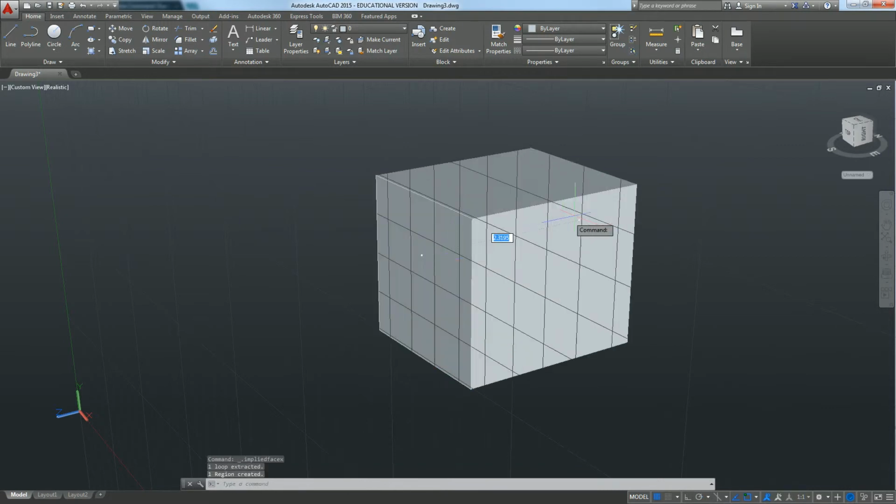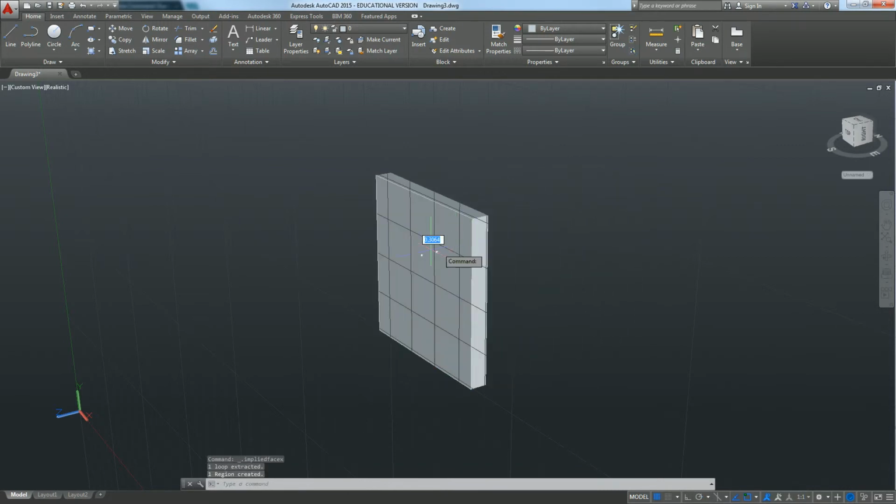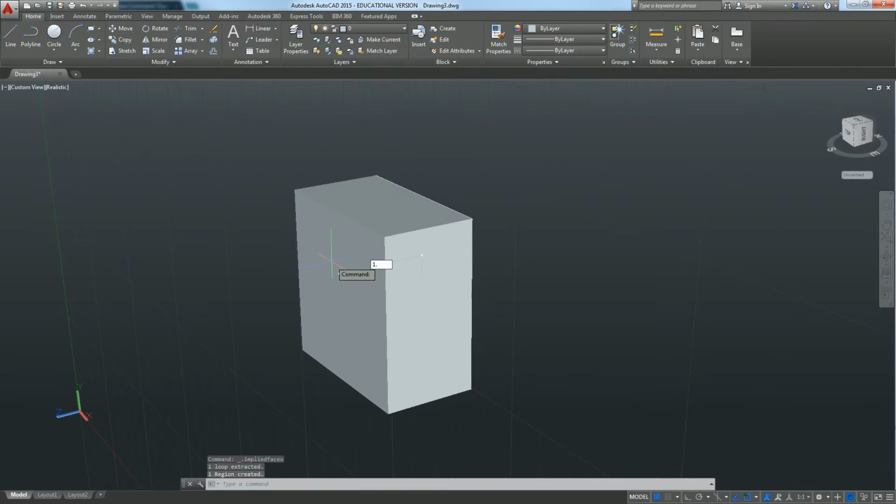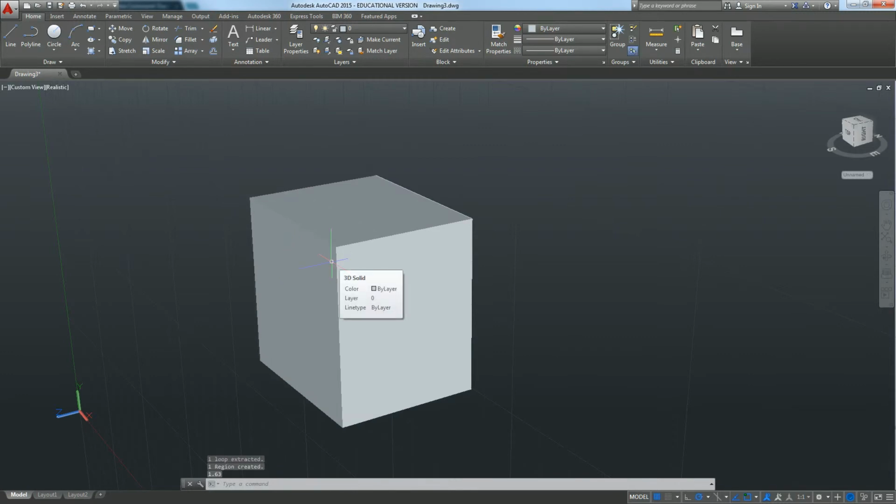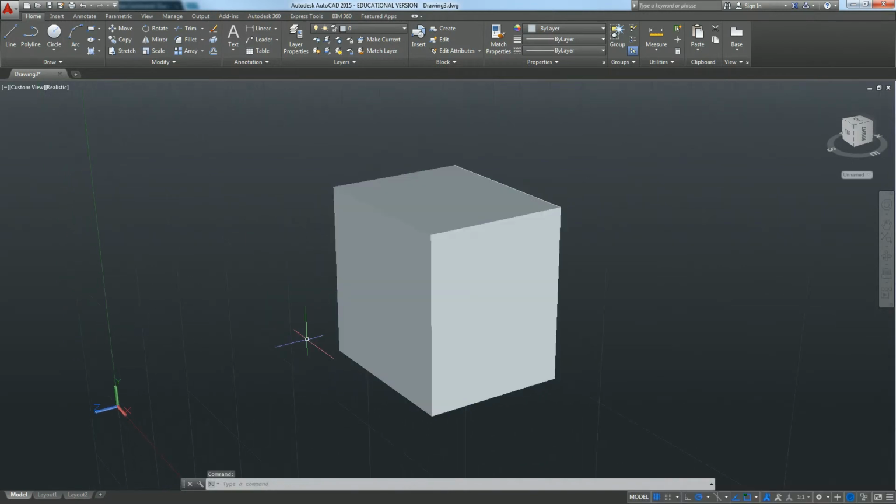And at this point, I'm just going to go ahead and press pull this 1.63. Now, on this rectangle, or on this basic cube structure that I'm working with right now, I have another rectangle that comes off the front that is perfectly centered on the front face here. So I'm going to go back to rectangle, and now I'm going to grab right here, and the software can look at the face of a 3D object, and this is giving me the 3D center snap.